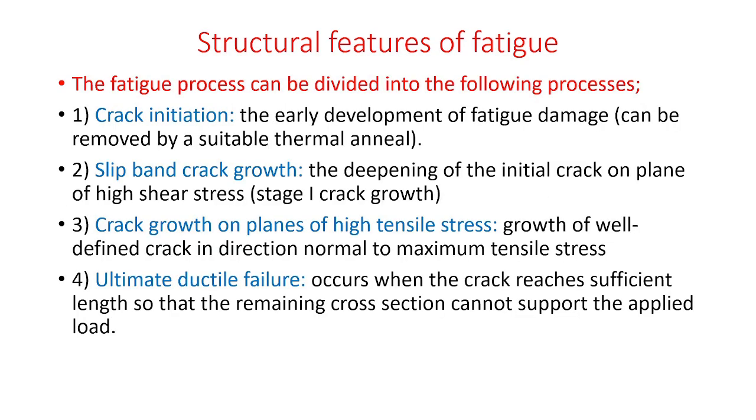Coming to the structural features of fatigue, we have already discussed that the fatigue process can be divided into various processes: crack initiation, slip band crack growth, crack growth on planes of high tensile stress, and ultimate ductile fracture. We can classify these into stage 1, stage 2 and stage 3. Crack initiation is the earliest development of fatigue damage. It can be removed by suitable thermal annealing.